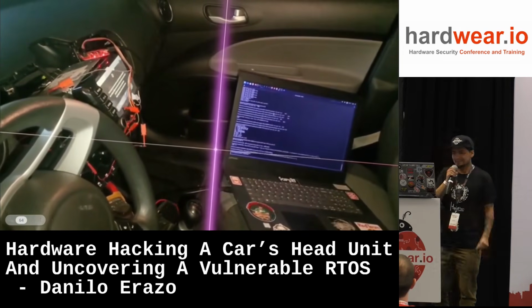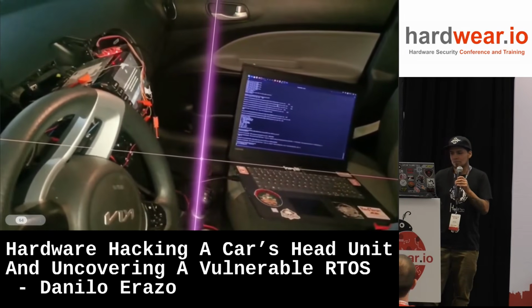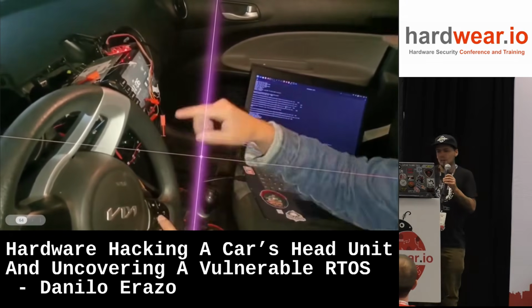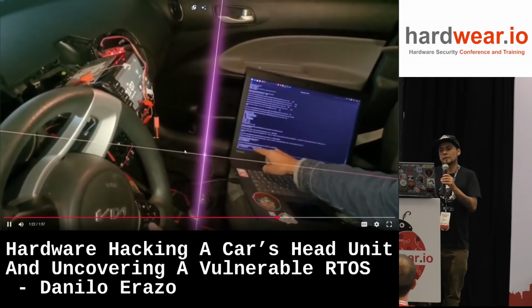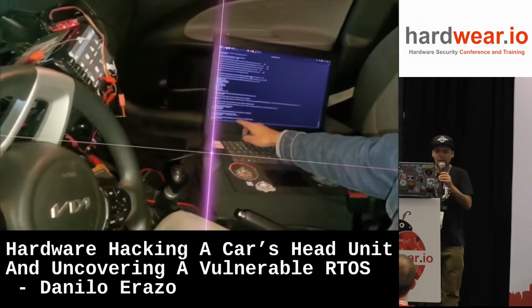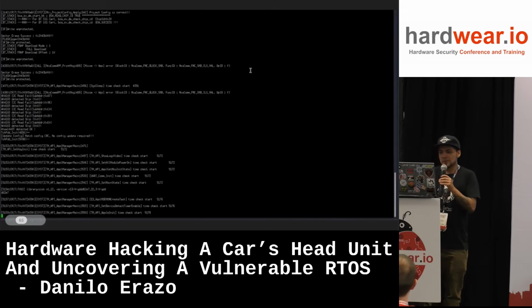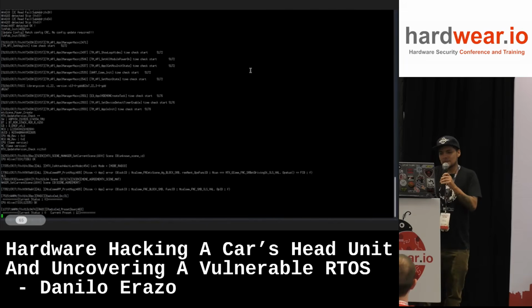Protocols information. This was the boot process. From here, if I press any button that shows up in the CAN network, I see the code here. For example, radio command press down 463. For example, I press settings, mixing manager set current scene. Bluetooth information is very interesting because I'm going to look for these functions' logs in the firmware.